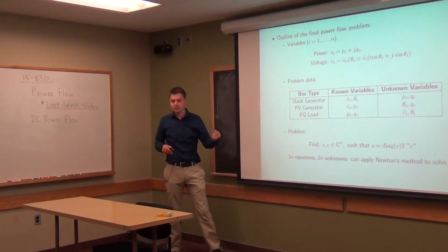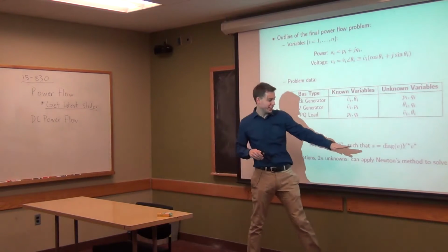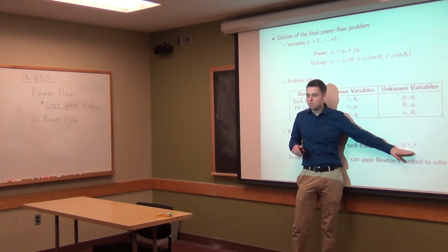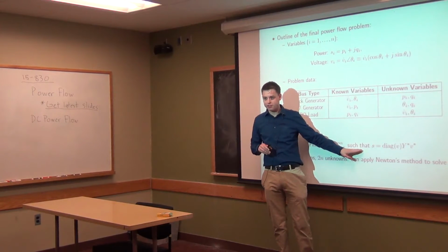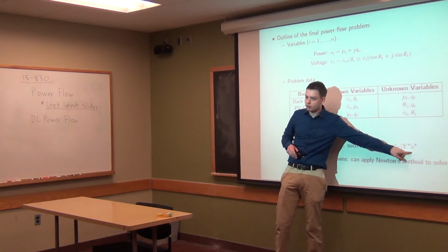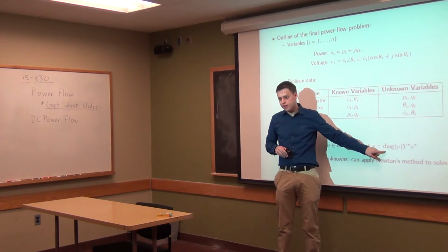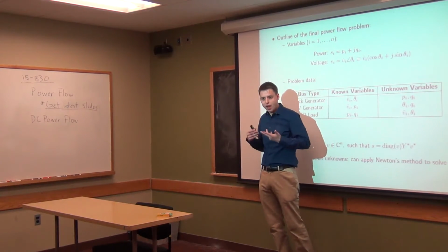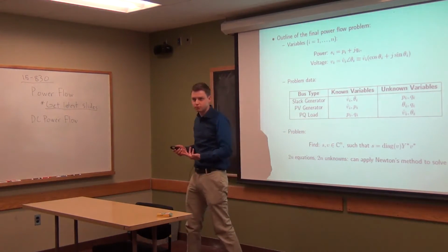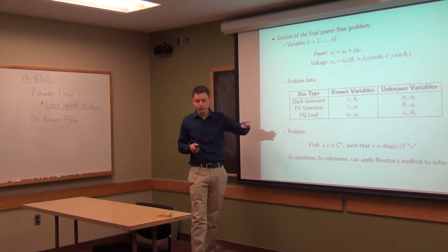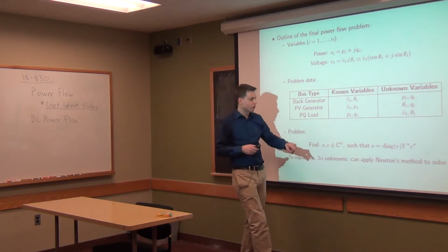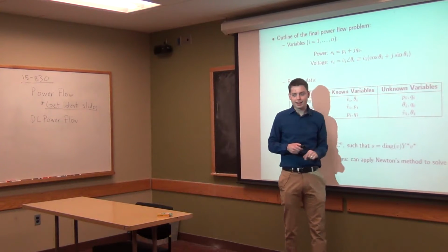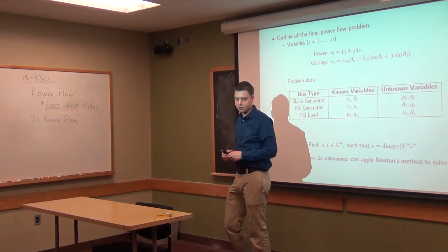And despite the form you might see later in these slides, people typically write a lot more complicated than this, but this is power flow here, just solving this equation. That's all it is. So keep in mind that we're doing something actually that's not that complex here. Just solving that equation, basically finding a 0 of this minus that, if you want to think of it in terms of Newton's method.